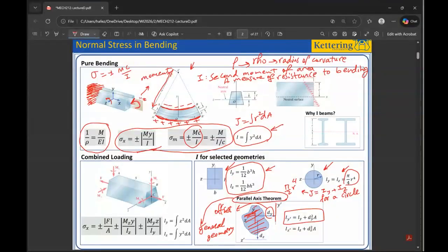So one side is negative, the other side is positive. Depending on the location of the point, you pick the sign accordingly. The textbook says the sign is the product of two signs, one for M, one for C, but I think it's really complicated. After teaching it for about 6 years, I think it's easy to figure that out geometrically. You bend it upward, visualize the deformation. If it shrinks or gets jammed or wrinkled, simply say it's compression, it's negative. Shortening is negative. If you're pulling, then it's positive.